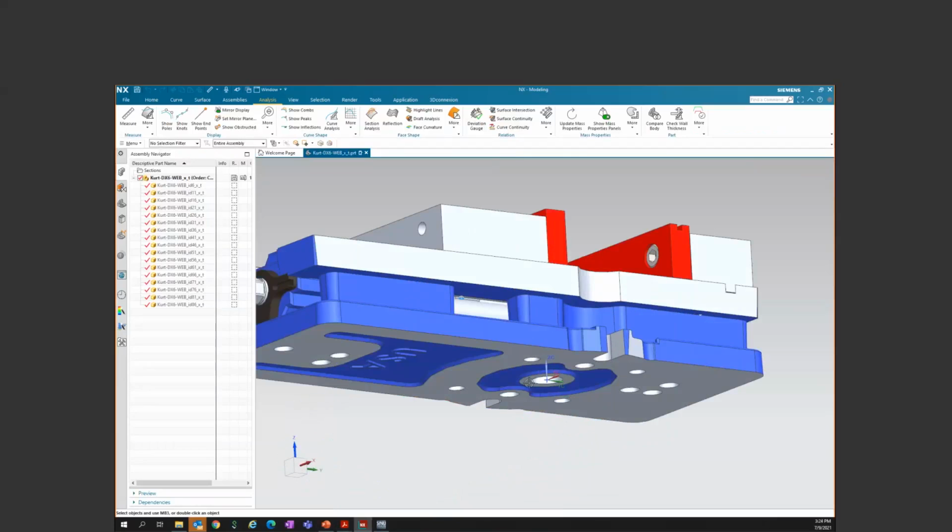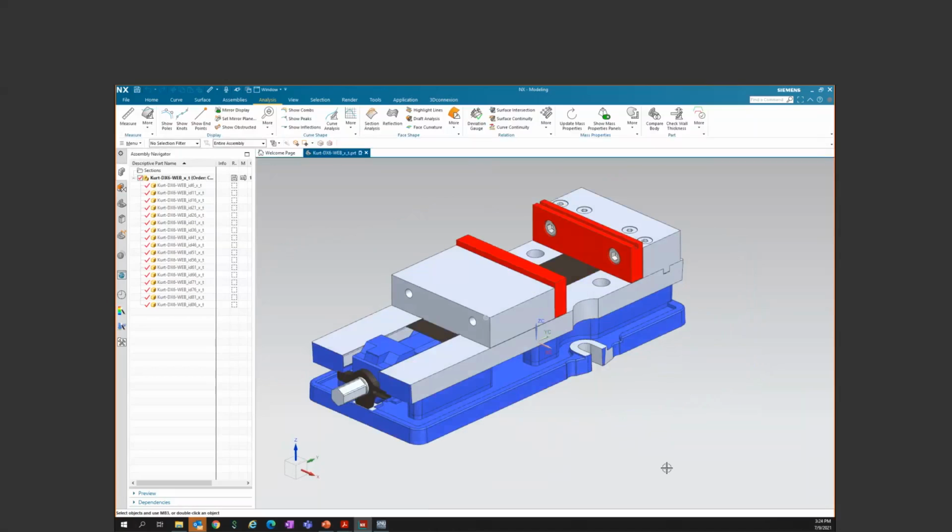So I had the zero set at the center of this bore, bottom of the vise. So that's a real tangible point in space for me to position this. So I can add that -24 and it's going to put this vise smack dab on my table. I put in an offset half the table width, half the table length. It's going to center this vise perfectly, giving me some known position where I can spatially get that vise and then mimic it when I get out on the floor, right? So let's do it.